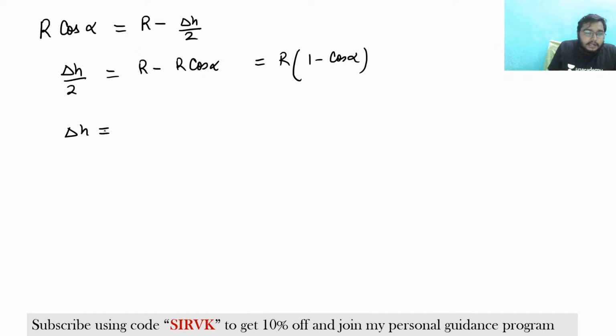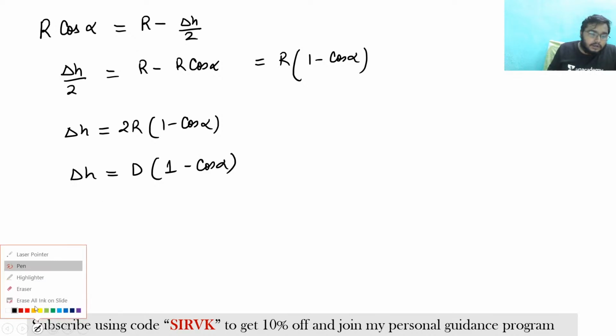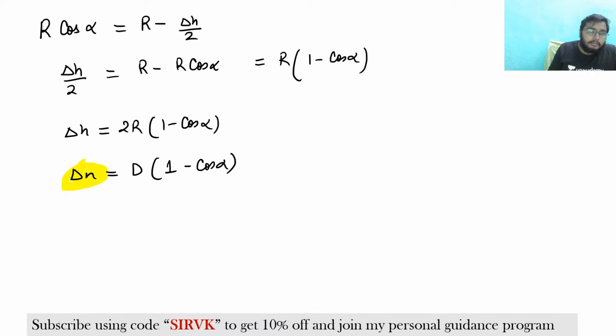So you can write delta H, there is a 2, so 2 will come here, so 2R into 1 minus cos alpha, and you will get delta H is equal to D into 1 minus cos alpha. So this is the good relation that you have got between delta H, the diameter of the roller, and the angle of bite.